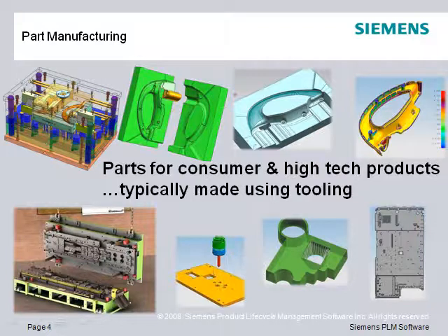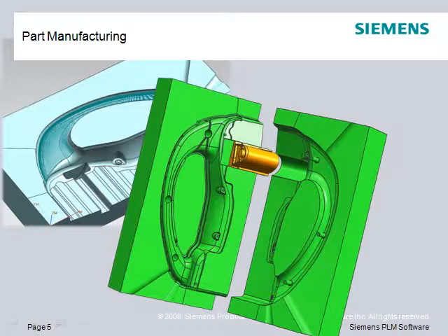The process to manufacture this type of part requires the extra steps needed to design and manufacture the mold or die tooling in order to deliver the required component. In this example, we will see one half of some mold tooling, manufactured to mold the case for a thermal imaging camera. The tool shape will be machined precisely from hard steels. Then this tooling is used within a plastic injection molding machine to produce the casting.